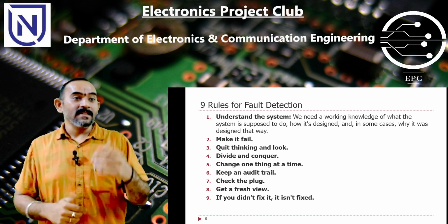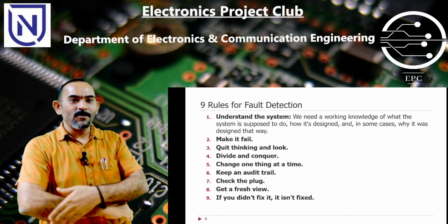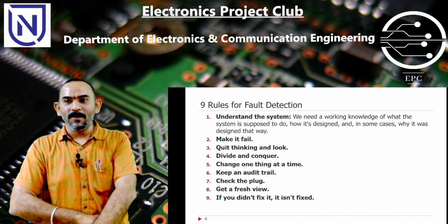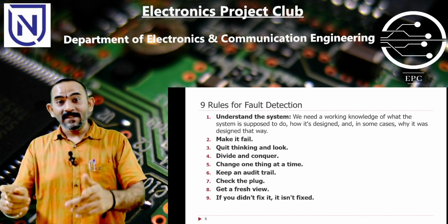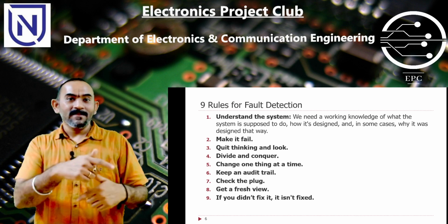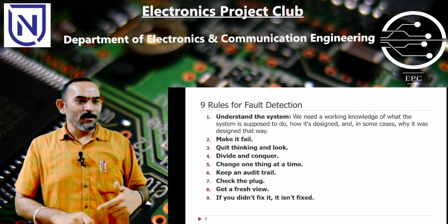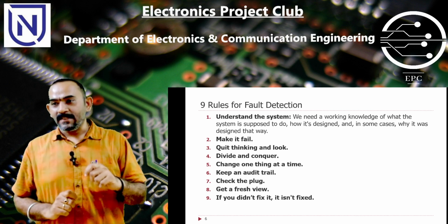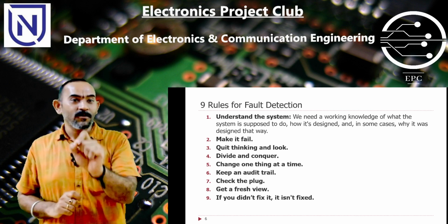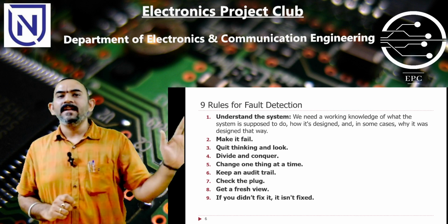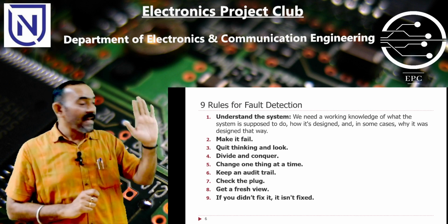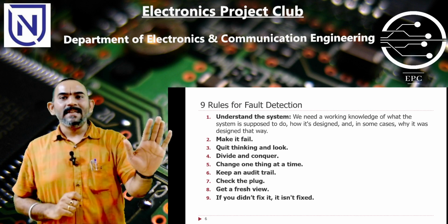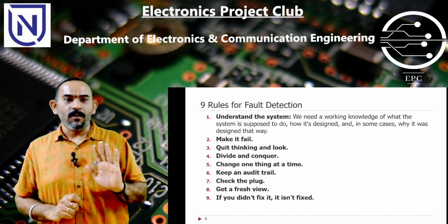Now one possible reason: some wire was loose, when you turned around your hand touched that wire and it made proper contact, and you are getting the output. I know it from my experience, but you guys don't know it because you are doing it for the first time. So unless you yourself fix it, you have to assume that it is not fixed. So these are the 9 steps for any testing or any debug, you have to follow this.